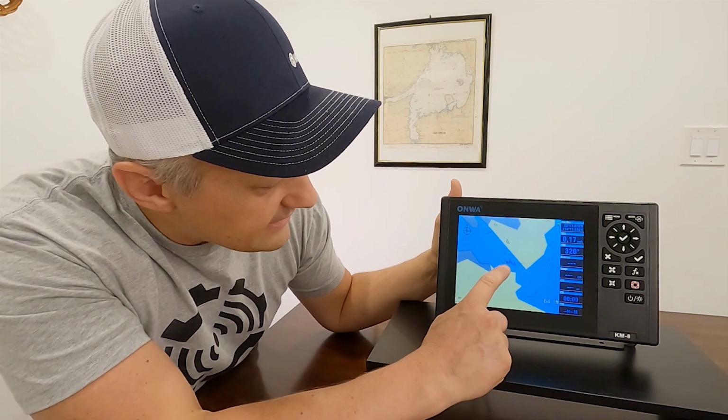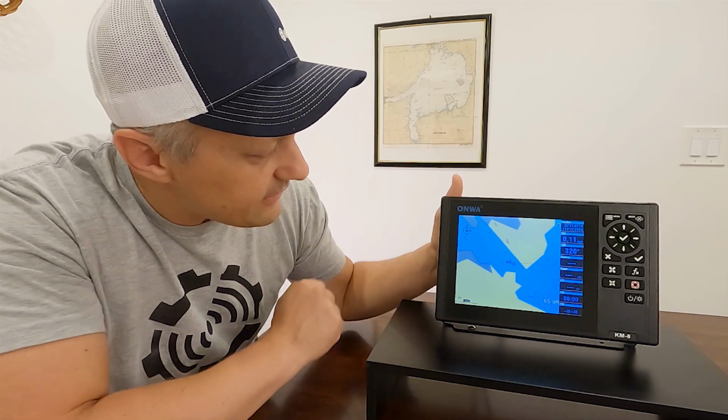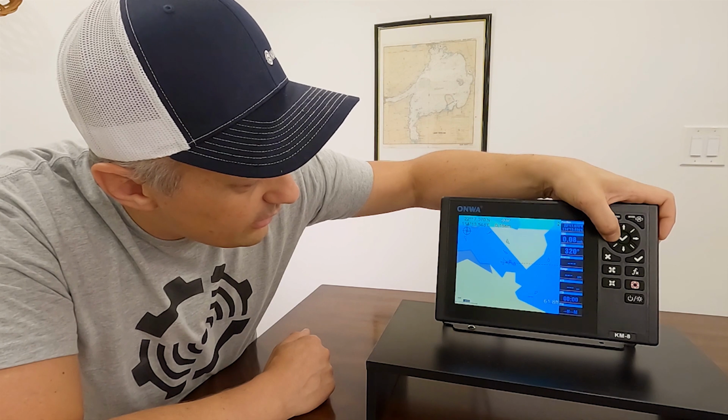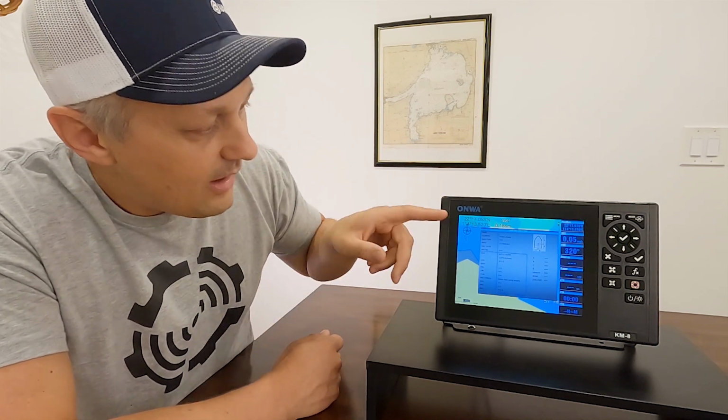With AIS, you have two options. You can receive, which would just allow you to see where other vessels are, or you can get a transceiver, which will allow you to transmit and receive. So you'll be able to transmit your position that any boat with an AIS receiver will be able to see you on their chart. So here I have an example of AIS targets being displayed on the plotter screen. Our vessel is indicated there by the red dot, and then these other AIS vessels are around us. So we can move our cursor over top of those and then get that information about that vessel.